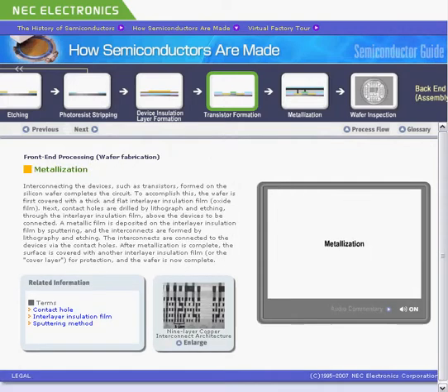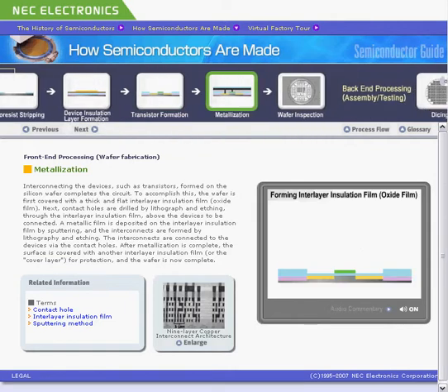The devices on an IC chip are interconnected to complete the circuit. Lithography is used yet once again to layer the insulating layers and the conductive metallic layers in the designated order, thus achieving a 3-dimensional interconnection of the circuit. The number of layers required for the interconnection tends to increase as the complexity of the circuit increases.